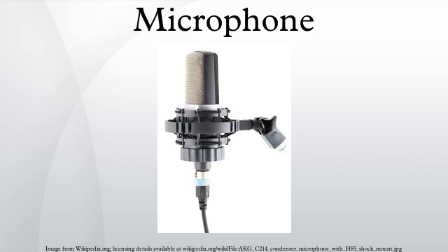The voltage across the resistor is amplified for performance or recording. In most cases, the electronics in the microphone itself contribute no voltage gain, as the voltage differential is quite significant, up to several volts for high sound levels. Since this is a very high impedance circuit, current gain only is usually needed, with the voltage remaining constant.